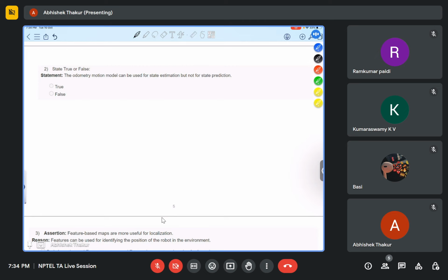So the odometry model uses the relative information of the robot's internal odometry. Let's suppose in time interval t minus 1, the robot has a pose x bar, y bar, theta bar. At timestamp t, it is going to x bar prime, y bar prime, theta bar prime.